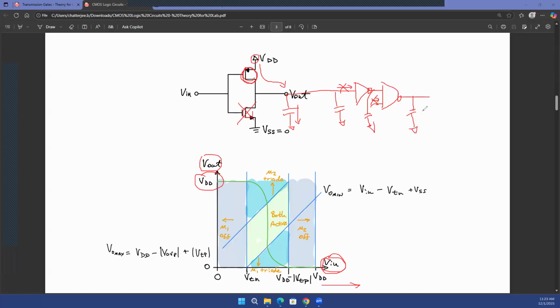So in digital circuits, because there is no current going into the gate of a transistor, which we already know, we do not have a resistive load. However, any point in a digital circuit will have parasitic capacitances, and that leads us to this parasitic capacitive load. Question?